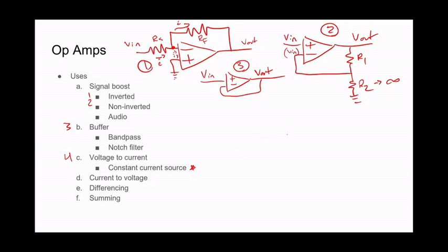Let's just say we have a motor, right? A really small motor, but it can draw different amounts of current depending on the manufacturer or things like that. So because this varies, we want to be able to have the same amount of current draw across that motor, no matter what the motor would prefer to have. We'll do that with what's called a transistor and an op amp and a constant current source.